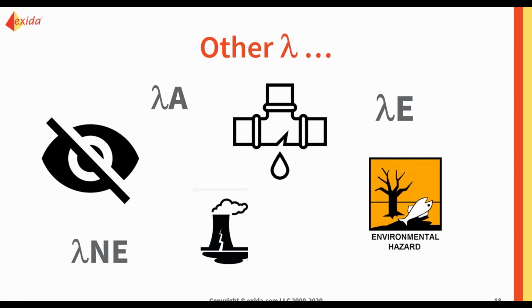There's a special type of no effect failure that's a subcategory, and that is the external leaks. This is broken out individually just in case you have a very hazardous or a very toxic process going through. You want to be aware if it's possibly leaking and could harm your employees or the people around you, your equipment, or the environment.